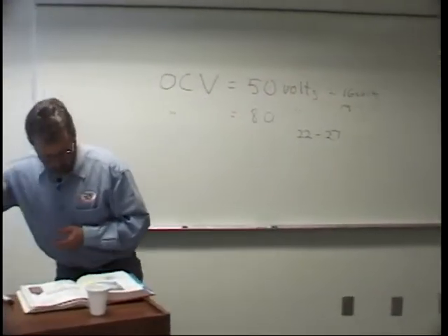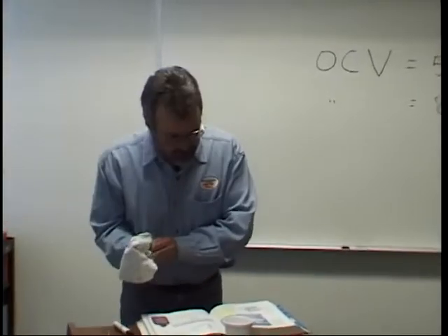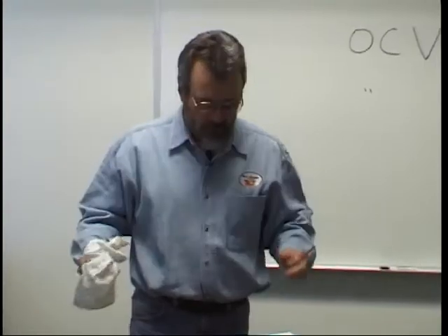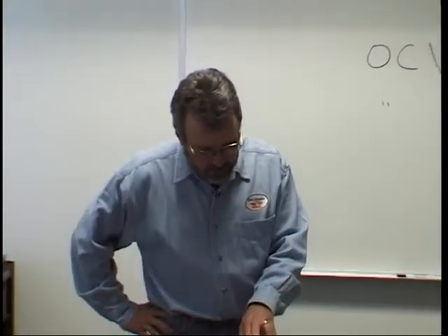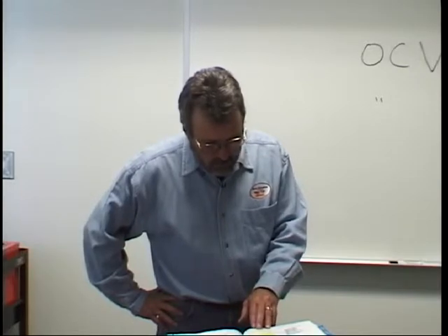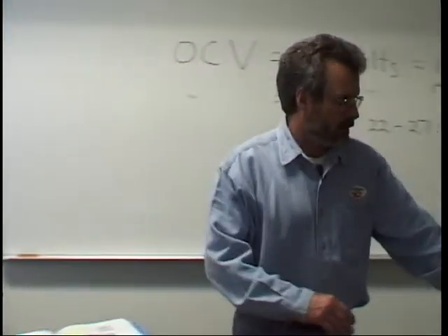Okay. So under cable assemblies, cable assemblies are an integral part of the gun. They generally consist of a single molded conductor that encloses all the necessary components. The electrical wire is guided through a flexible liner contained in the cable assembly. The liner is made of spring steel for strength and protection. And this is a liner.